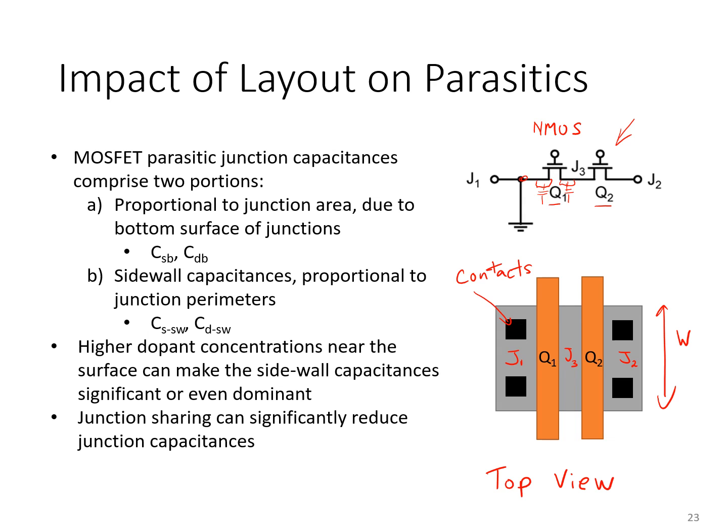And so it would have less area, and therefore we would expect less parasitic capacitance between J3 and the body region, which, although we haven't shown it explicitly in the schematic, when we fail to do so on an integrated circuit, we assume that NMOS body regions are connected to the lowest voltage anywhere in the circuit, or ground, right? Typically ground.